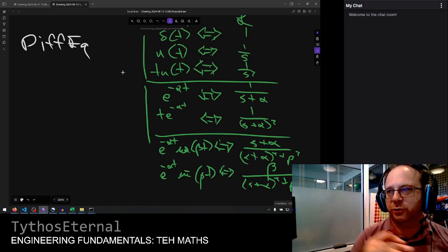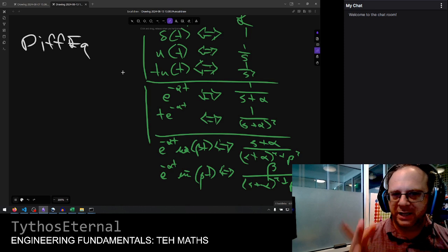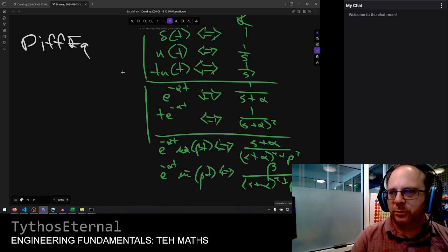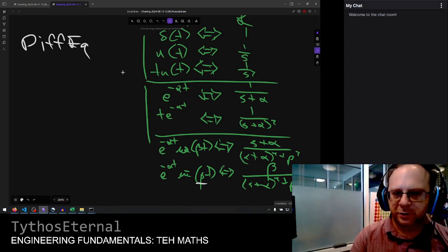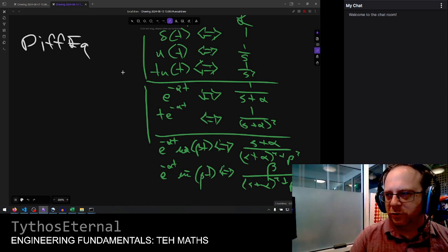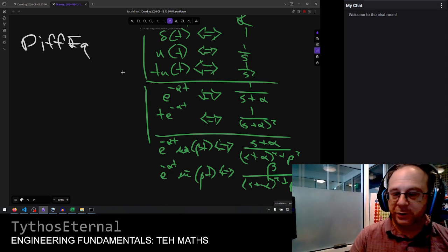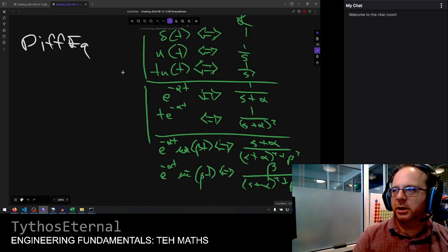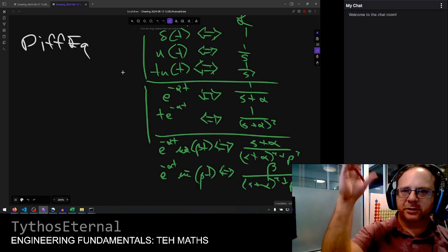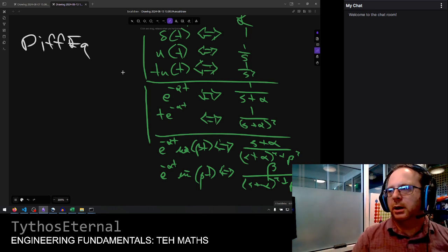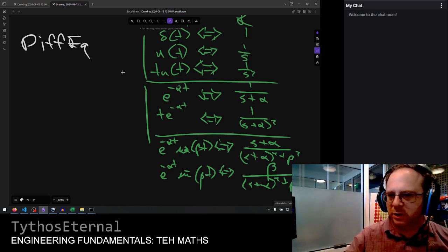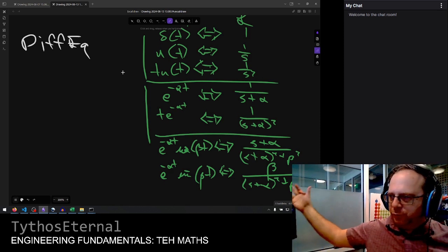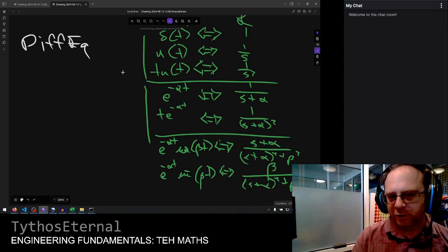So even for a 10th order system, there's one particular dynamic in the transform, and then constructing that as a function of the properties of the system, you can say, well, it's going to have this frequency, and that's going to be much higher, and you need to worry about that, right? So that's too fast, or the airplane's going to turn too slow, the autopilot's going to induce an oscillation or something like that. Being able to characterize the system even for multiple orders of terms as decompositions of these second order systems is